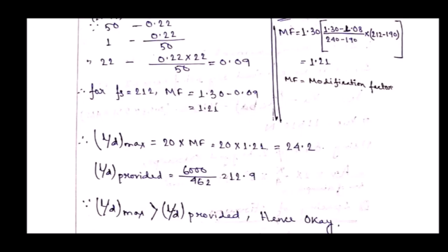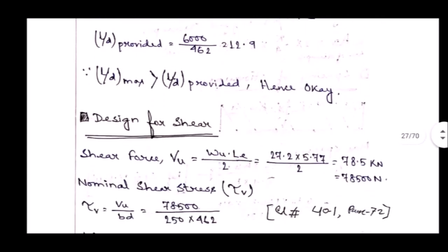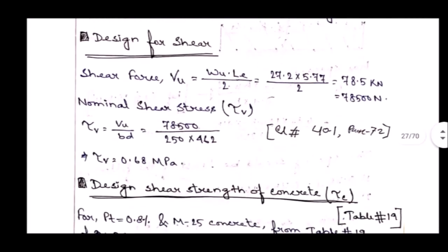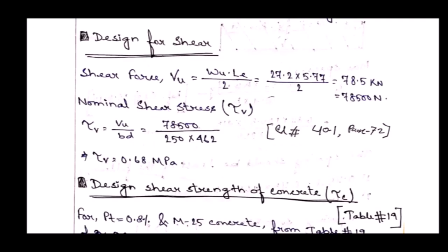Let's go to the next step. The next step is design for shear. We have to design shear also. For shear, we have to provide reinforcement, and that is called stirrup, or shear reinforcement. So first of all, we have to find out the shear force.